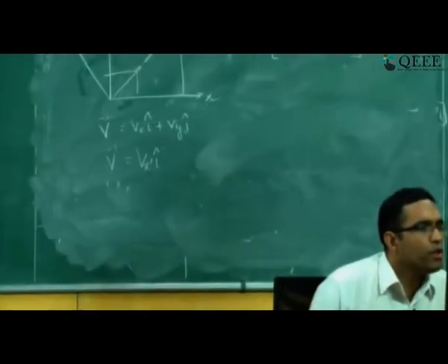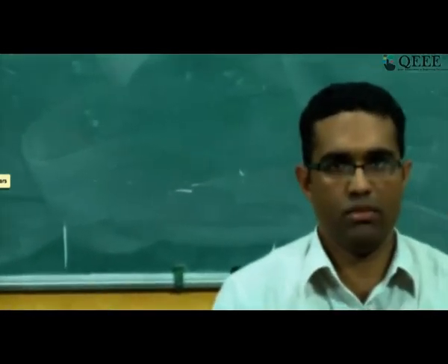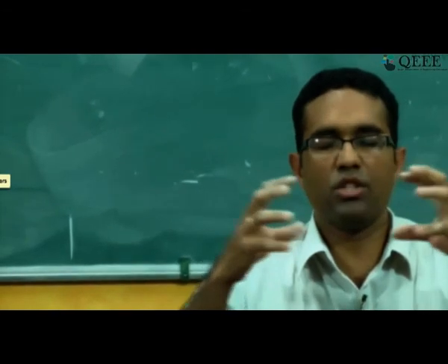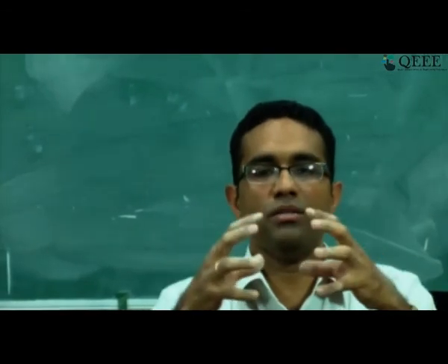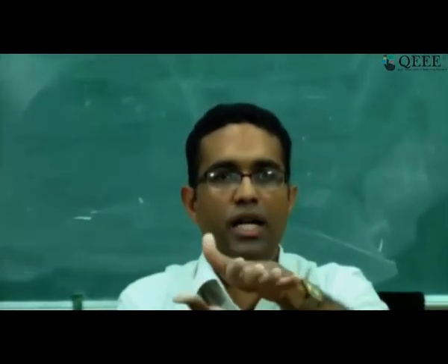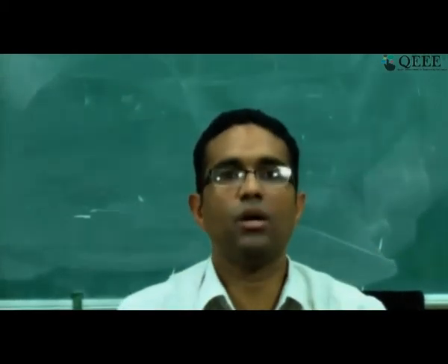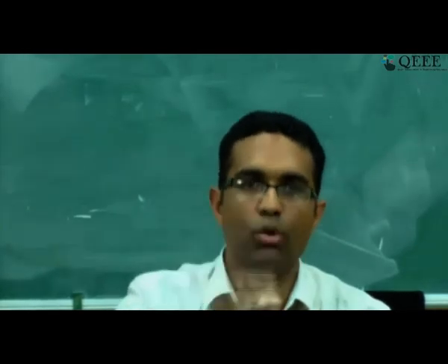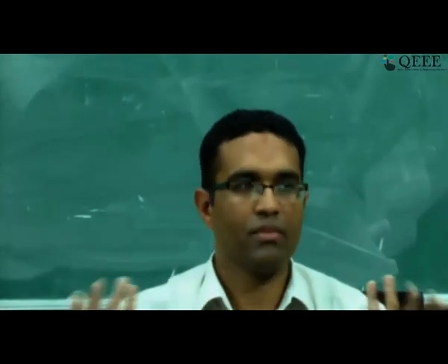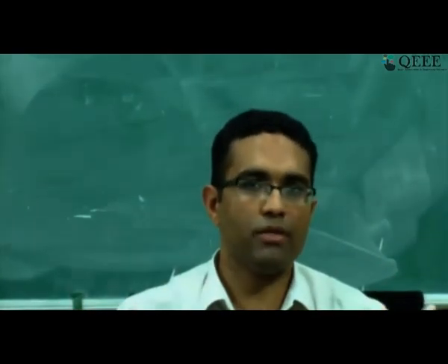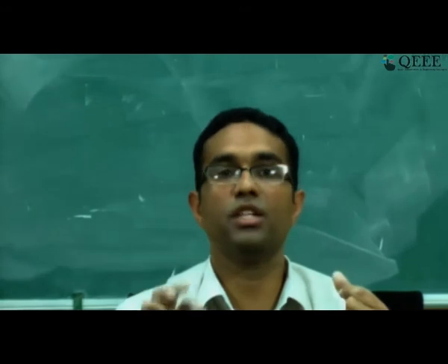What is the influence of deviatoric stress in a material? Deviatoric stress causes a change in the shape of the material. It doesn't cause a change in the volume. Instead, it makes a cube into a cuboid, it shears it and does all sorts of things. Only if deviatoric stresses are acting on a particular material will the dislocations in that material move. If it is purely a hydrostatic component, the dislocation will just stay there, which means it will not yield. So the von Mises theory is basically independent of the hydrostatic stresses and dependent only on the deviatoric stress, or rather the deviatoric strain energy density.